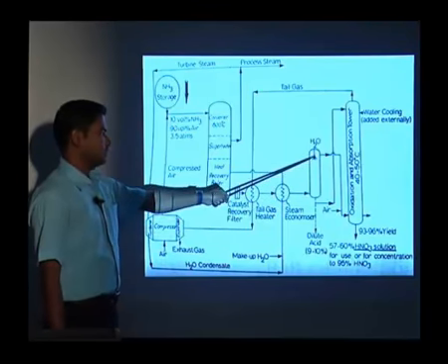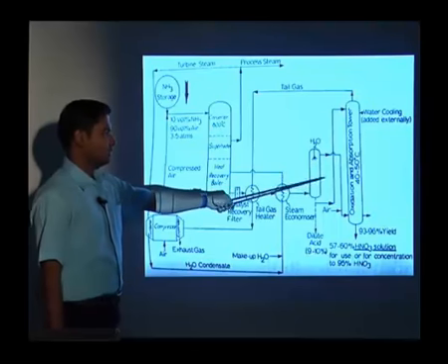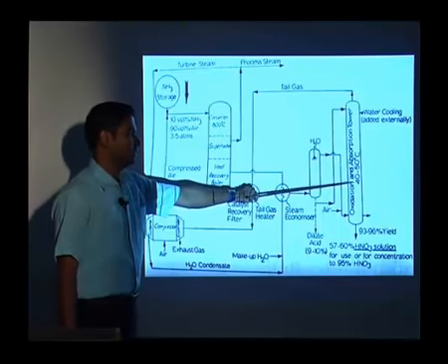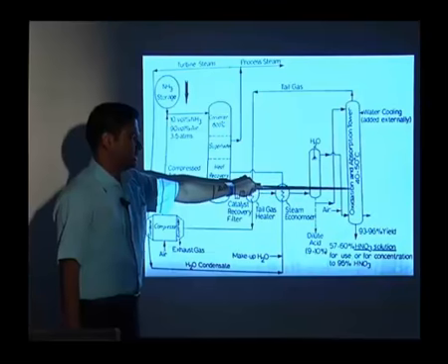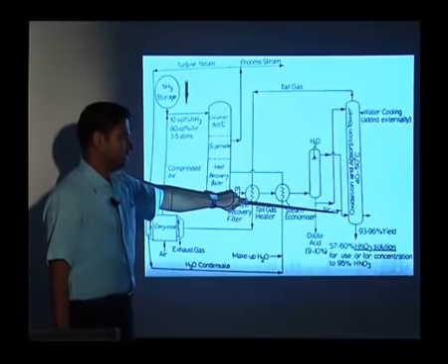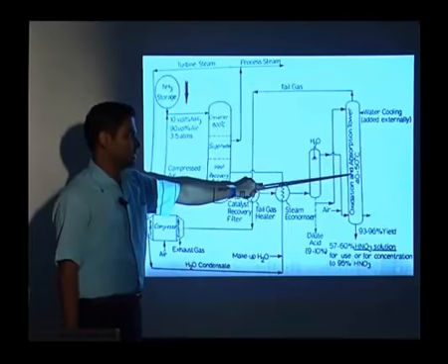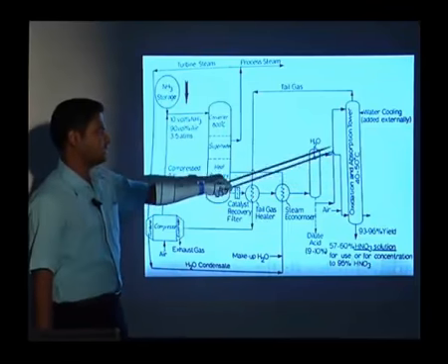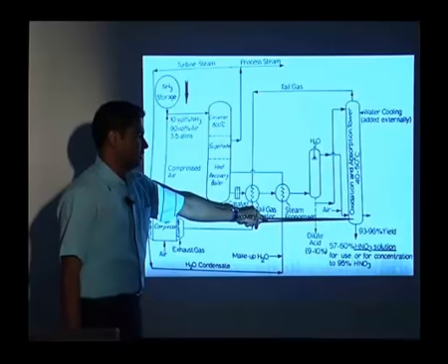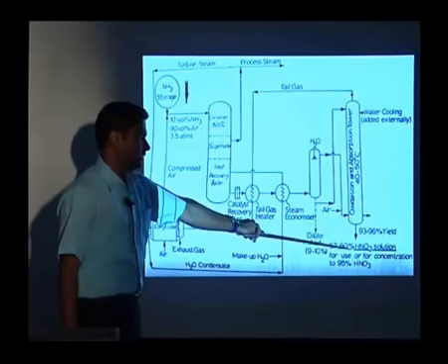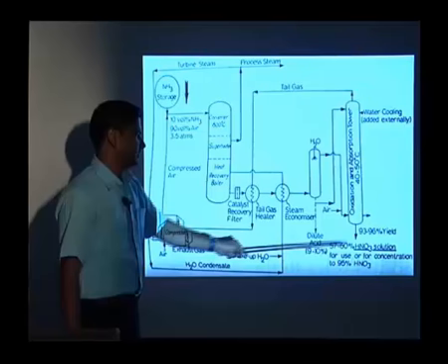And then again we are cooling with the help of water to get the NO in this reactor. In this one, air is added to the NO to form NO2. This reaction will take place at 40 to 50 degrees Celsius. And then whatever nitric acid we are getting, we can send to the storage.